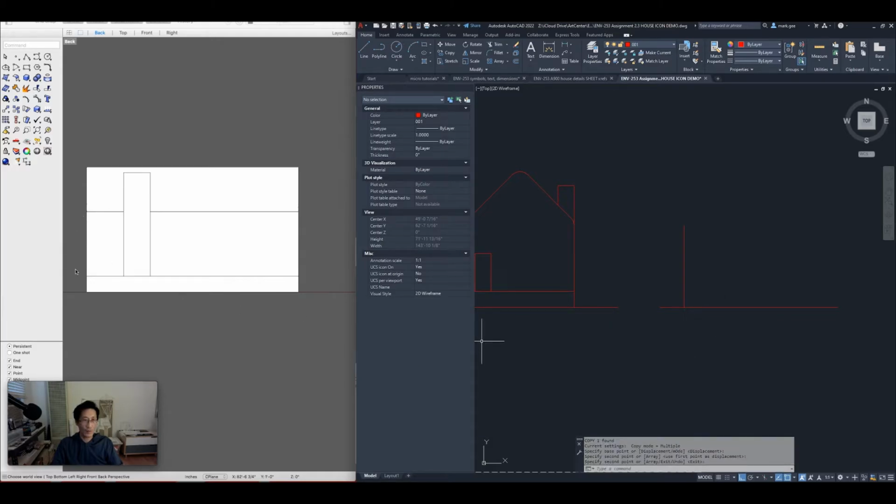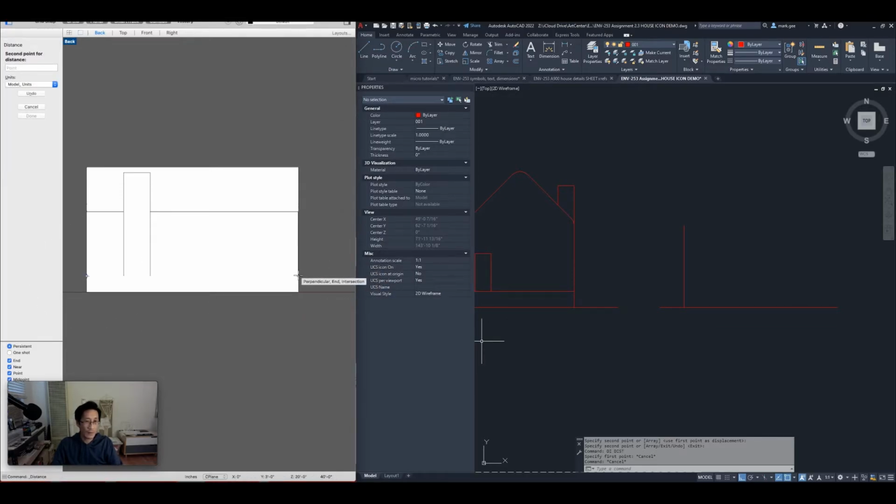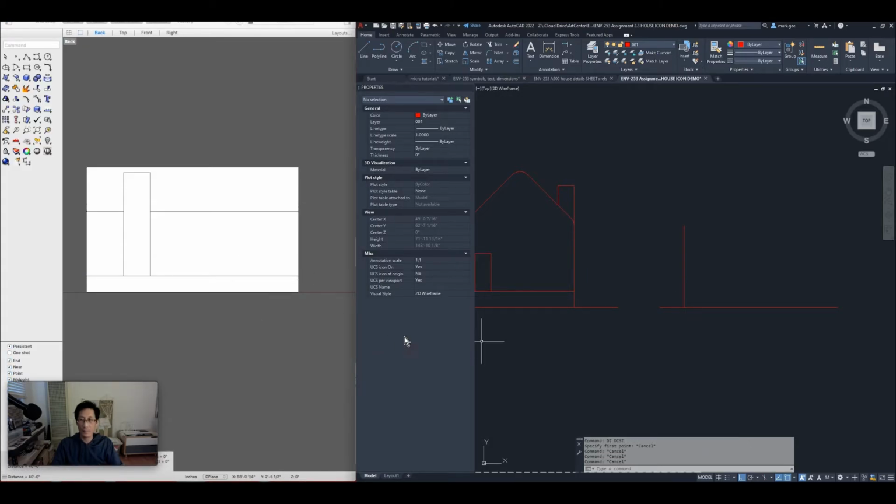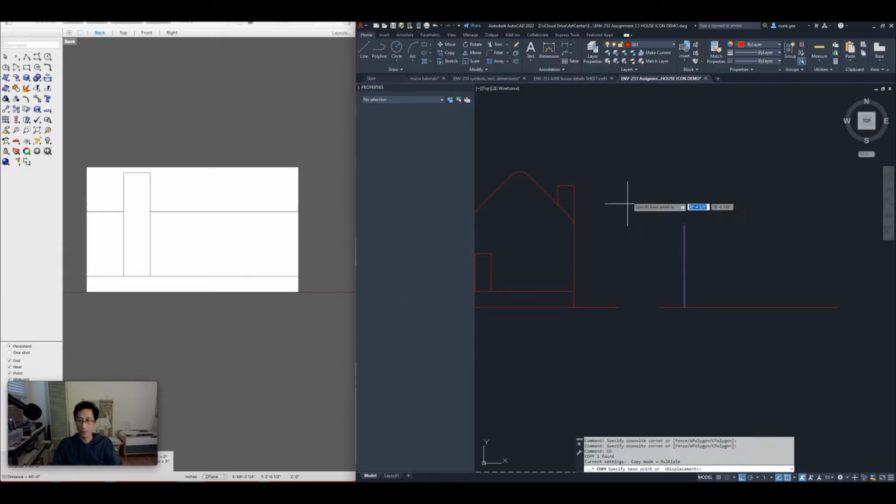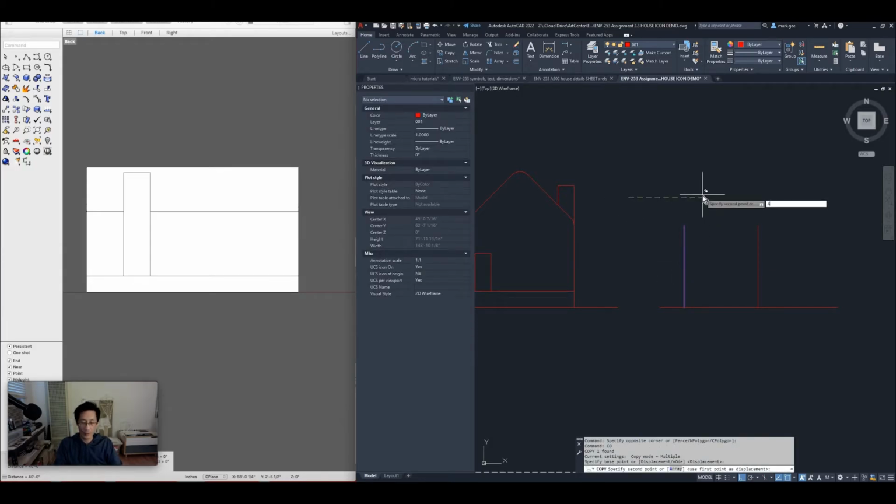Let's check some dimensions here. All the way across this face, do dimension. Whoops. Go back to Rhino. There we go. Dimension. So across here, that's 40 feet. So we'll copy, whoops, this line, CO, 480 inches, which is 40 feet. Enter. It's off the screen. I'll go ahead and stretch S my ground plane here to extend beyond that. All right.